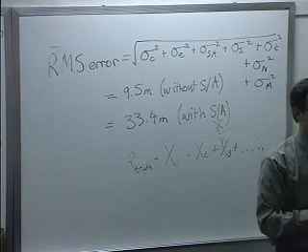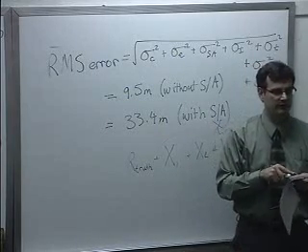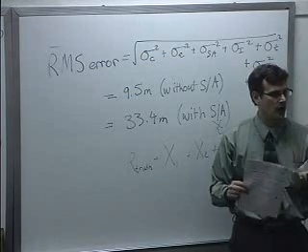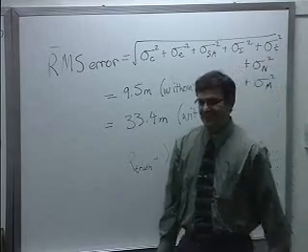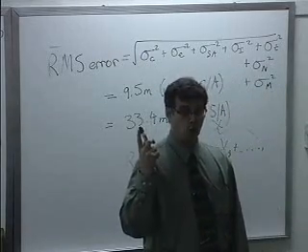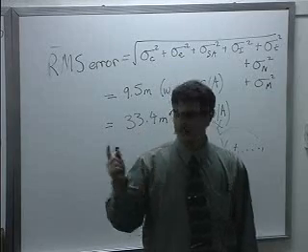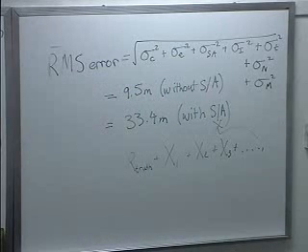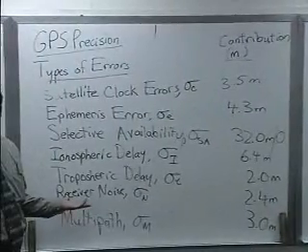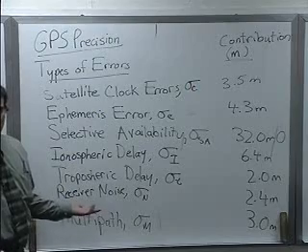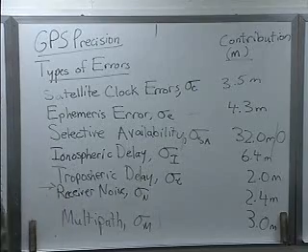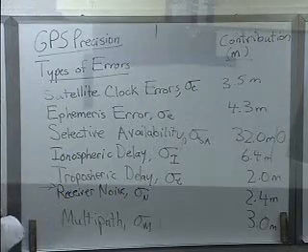William. What does this differential GPS work to knock down so that your signal is like 40 centimeter accuracy? That's a great question. So the question is, which of these can we knock down? And it turns out that some of these on the list, if we go back to this list over here, some of these we don't have any control over. Take a look at receiver noise. Can we do anything about receiver noise? No. It's unpredictable. There's one thing we can do about it. We'll talk about that in a second. But for the most part, I can't do anything about that. Multipath, can't really do anything about that.